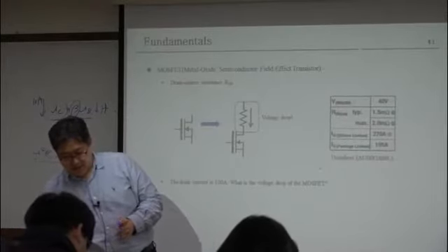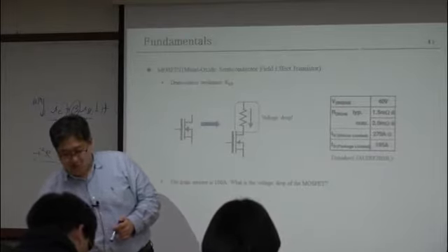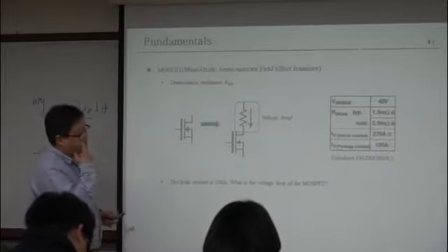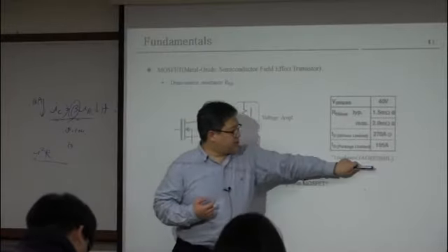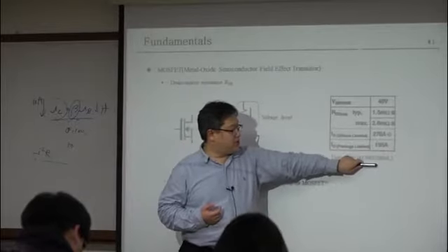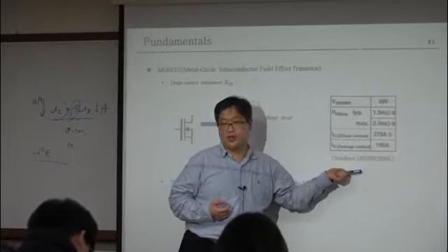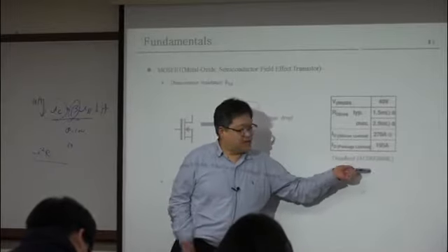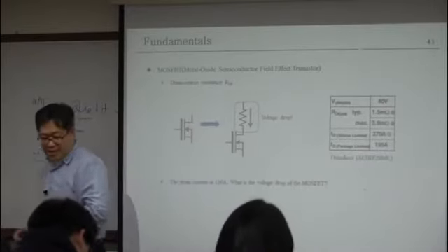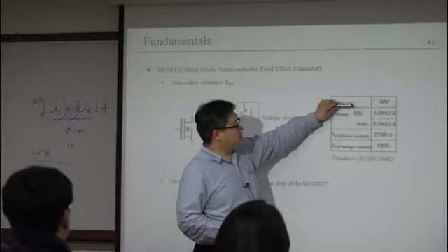this case here. In fact, this is the MOSFET called AU-IRF 2804L. Here AU means automotive grade. IRF is the International Rectifier company. And VDSS is 40 volt.